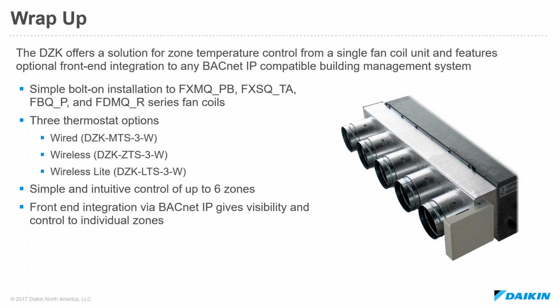DZK is also commonly used if ASHRAE 15 becomes a challenge on a project and we are trying to give zone level control, but we need to duct to several rooms because we're serving very small rooms. The DZK can be a good solution to address those ASHRAE 15 limitations on larger systems.